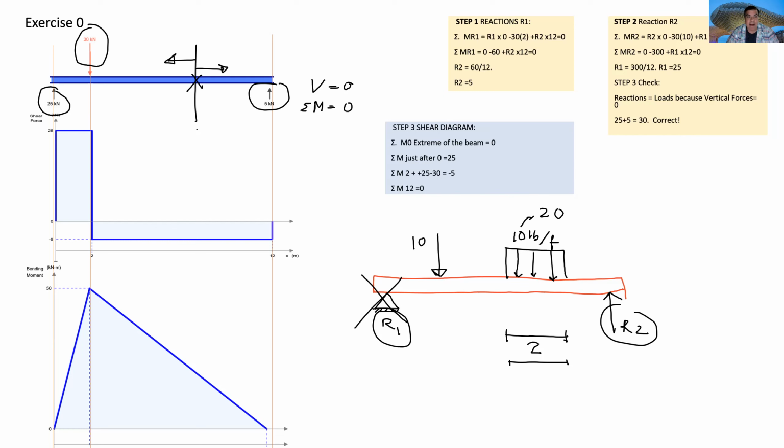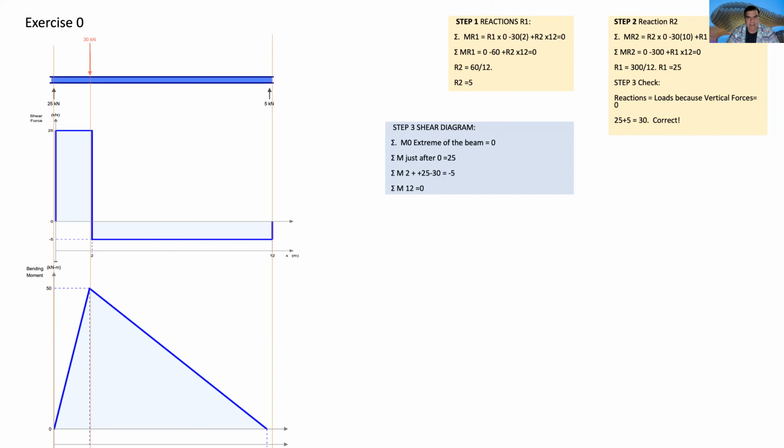Also, a beam has a maximum shear. Today we'll be calculating the maximum shear. As you know, a beam will usually fail because of bending moment, but we need to check if the shear is adequate or not. That is what we'll be doing today. We will be calculating the maximum shear of that particular beam. Calculating shear is not something difficult. It's exactly like doing a balance in a bank.